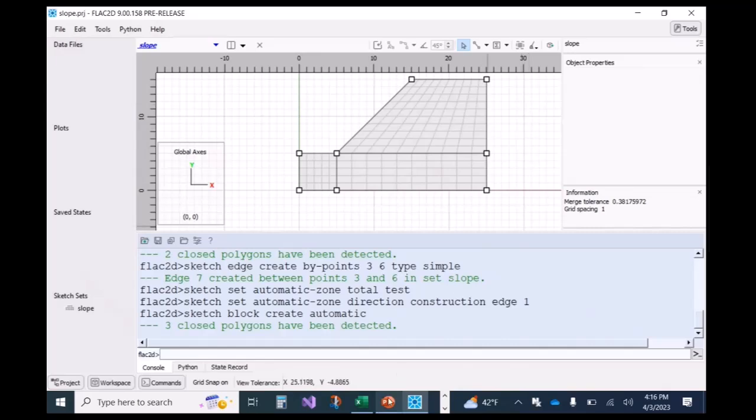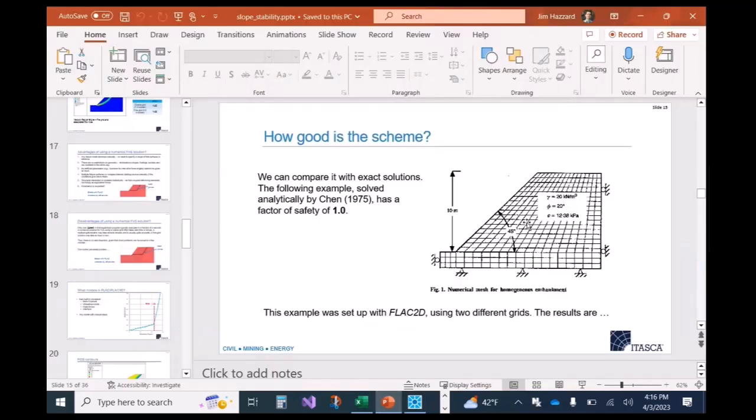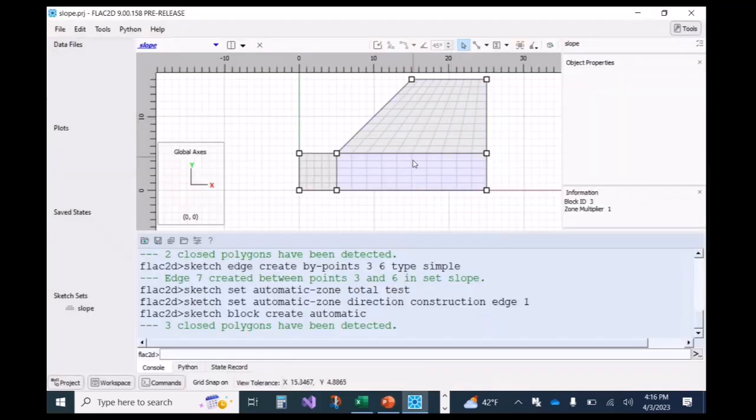This is a little bit coarser than this one, but run it just for fun. I think this will actually run with the demo. This will definitely run with the demo version. Less than 1,000 zones. If we have time, we can come back and make it denser. But we're basically done with that. So we can create the zones. Press this little create zone button.